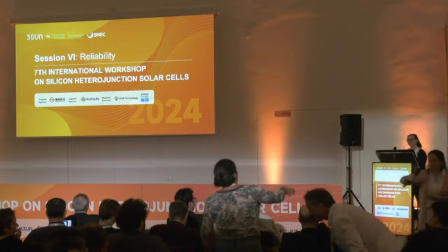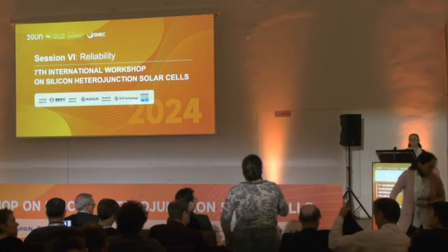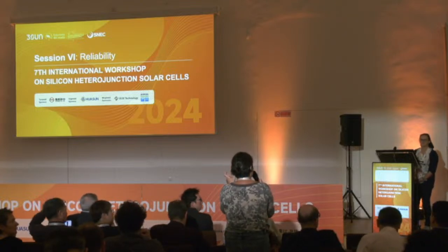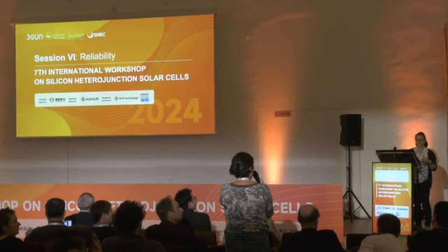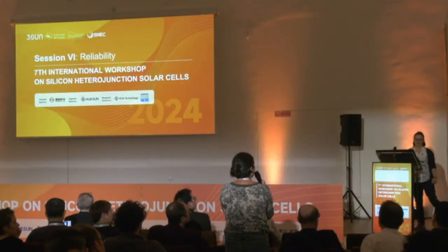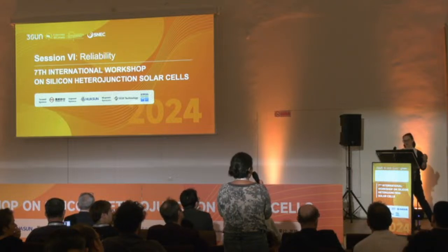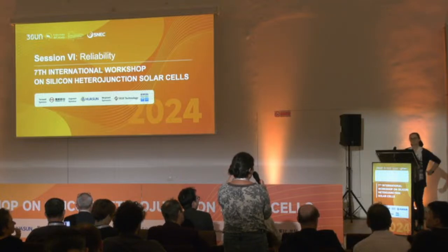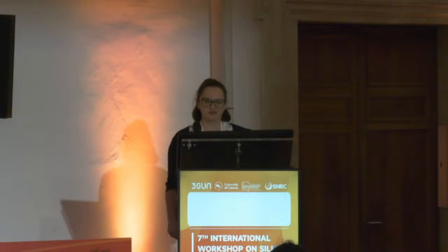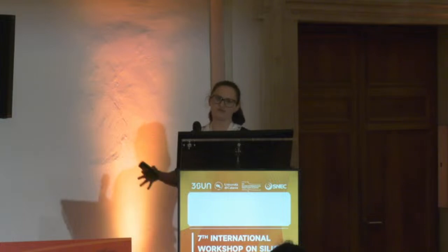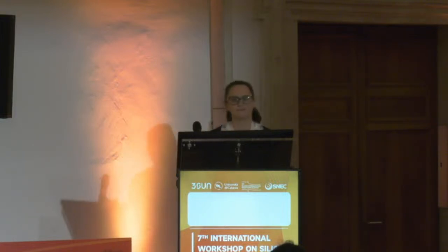I have one question regarding your bifaciality assessment. When you say bifacial and monofacial, it's only for PERC structures. Right, yeah. So the silicon heterojunction modules did not have a monofacial counterpart, but the bifaciality was still calculated from simulation. So you don't know if in the case of heterojunction, you follow the same trend. For the case of silicon heterojunction, the factor is still calculated, but there's not a monofacial counterpart that's fabricated and fielded there. Okay, thank you for clarifying.